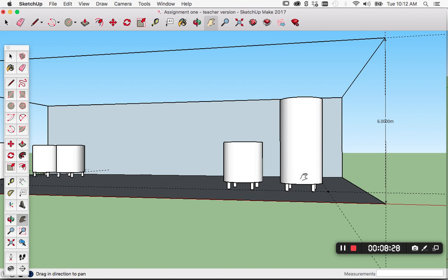But as we transfer it, the height of liquid in the discharge tank begins to increase. This one decreases, so our static head will increase, the difference between the height of the liquid in the supply tank and the height of the liquid in the discharge tank. The maximum will be when we're finally filling up this discharge tank after pumping 2 supply tanks worth in there. So after we pump 1 tank in, it'll be half full, because they're the same diameter, and the supply tanks are half the height.